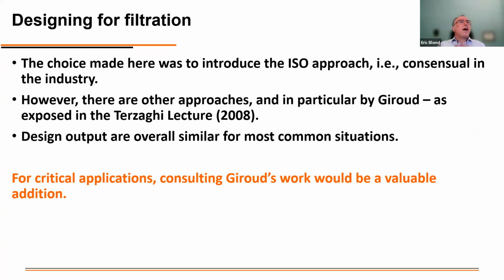The truth is that there are other design strategies which are available, and one of the very important ones is Giroud's approach to geotextile filtration, as he has exposed in the Terzaghi lecture. This solution was not retained by the group for a variety of reasons, one of them being the way he creates approximations of soil properties, which leave space for discussion.